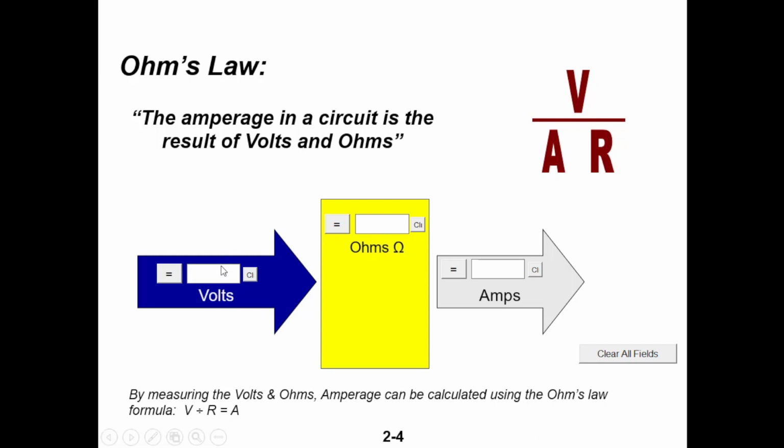So in this example, I'm actually going to plug in some really basic numbers. We'll start with a 12 volt circuit, which is an automotive battery, we'll say 12.6 volts. And let's say my starter needs to draw 100 amps. Well, we can figure this out by using our math. We would divide 100 into the 12.6 volts to give me how many ohms would be in my starter. If I press this equals button, you can see that the starter ohms are very, very low. They're not even a full ohm, right? They're 0.126, so a very, very small amount of ohms in a starter.